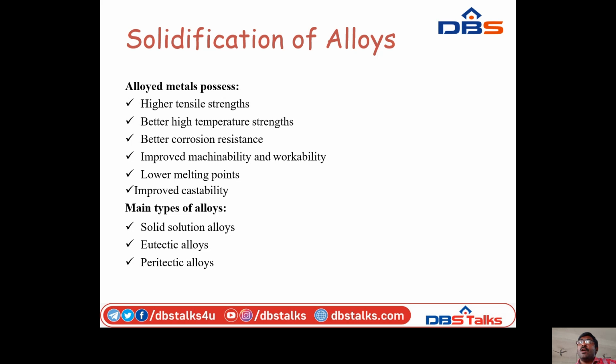Solidification of alloys. Alloys possess high tensile strength, better high temperature strength, better corrosion resistance, improved machinability and workability, low melting point, and improved castability. Main types of alloys: solid solution alloys, eutectic alloys, peritectic alloys.